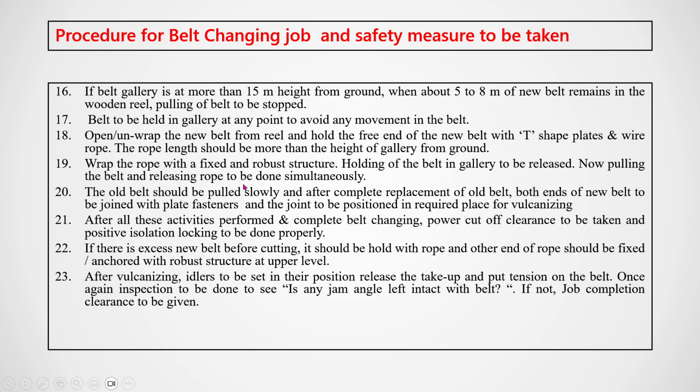and pulling the belt and releasing the rope are to be done simultaneously, and you can do both operations in a single job. Then you have to tie the old belt with the new belt, and I will show the picture of how to do that. Then after all these activities, perform complete belt changing. Power cutoff and clearance for the positive isolation have already been discussed.